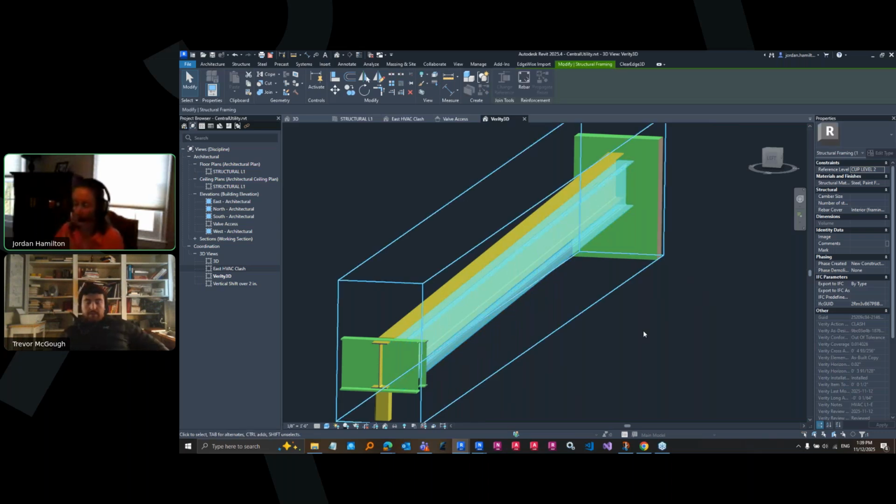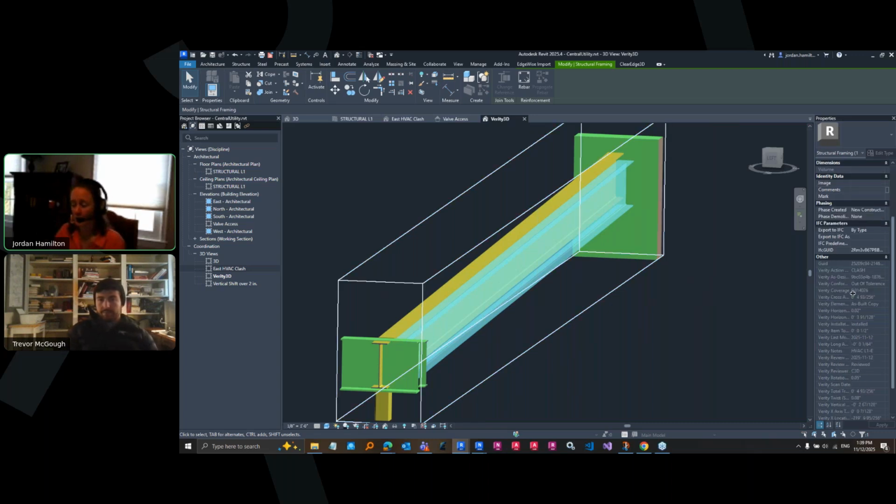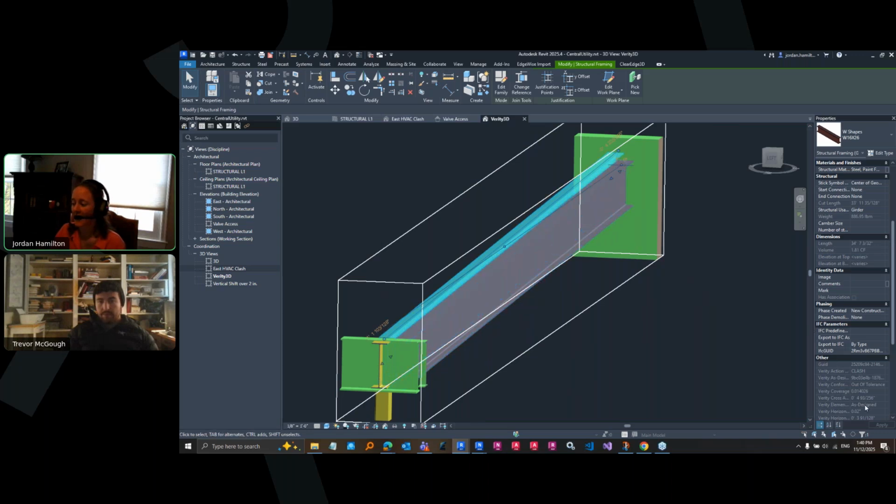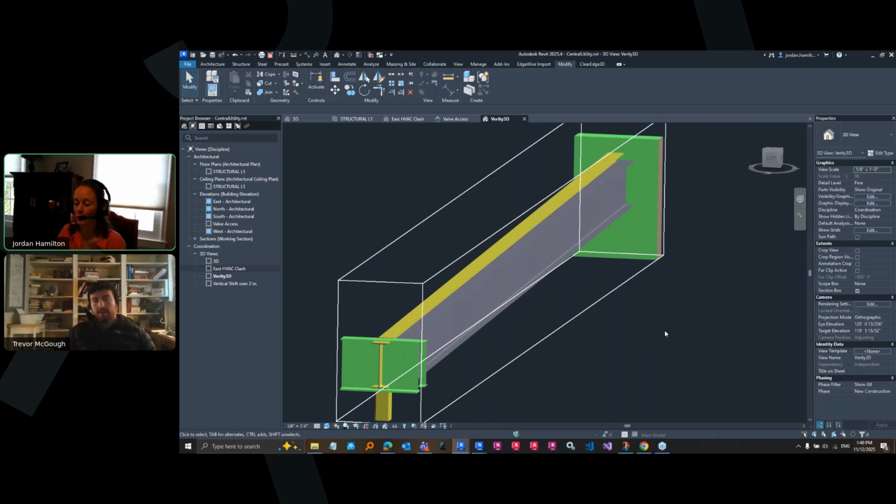As you can see, all of the Verity information from the original object is still noted in the properties of this as-built copy. The main difference here is that this copy item is tagged in the Verity element type as an as-built copy, whereas the original is tagged as the as designed, which again means that you can now set up a view for only viewing Verity as-built objects, or create a filter inside of your current view to only show the as-builts. Anything like that, you now have your true as-built location represented.